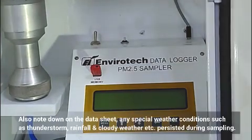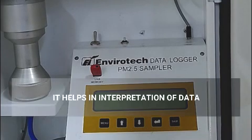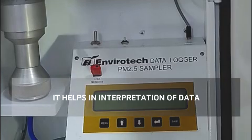Also, note down on the data sheet any special weather conditions, such as thunderstorm, rainfall and cloudy weather etc. persisted during sampling. It helps in interpretation of data.